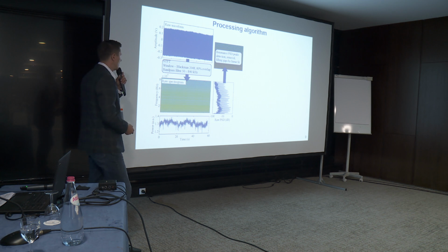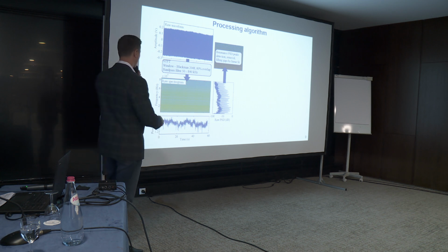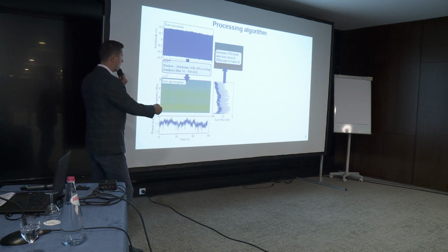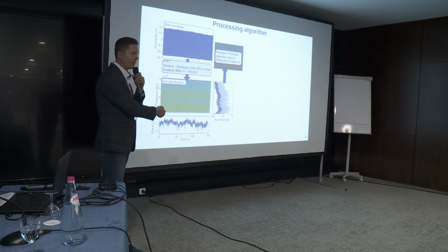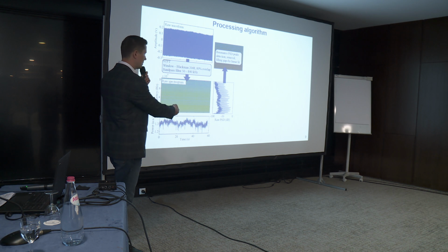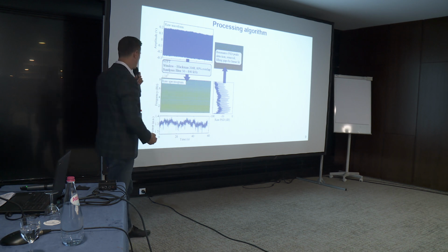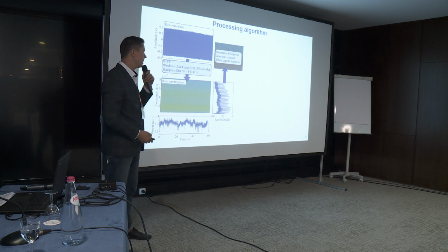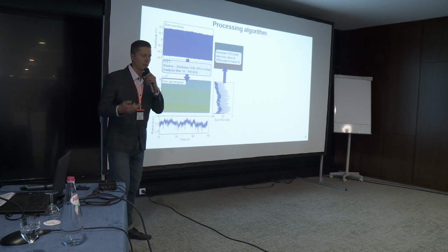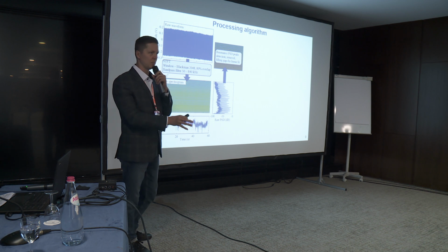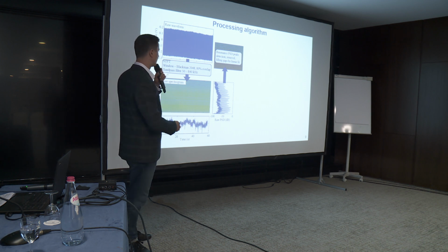If we do a short-time Fourier transformation, we see that our power spectrum looks really like a brush for your hair. These peaks come from the resonance frequency, 20, 40, 60, and so on. So how could we filter this out? Of course, not using just a physical-based broadband filter.